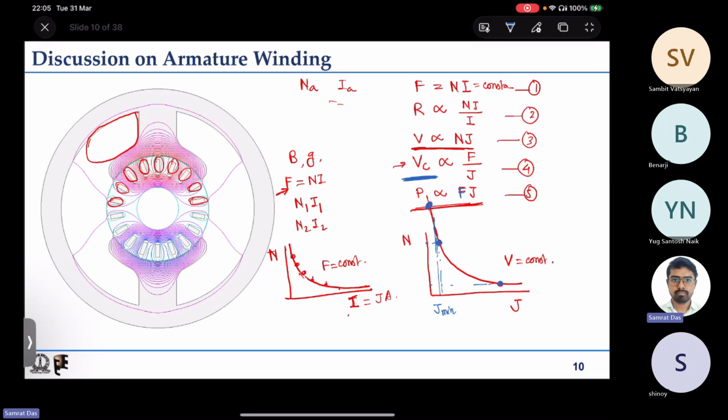Okay. So as soon as the volume we have at our disposal is fixed, and we know the mmf that we want to create, then the minimum current density that we can go to is fixed. So that is the J min that we have. That is always another constraint.